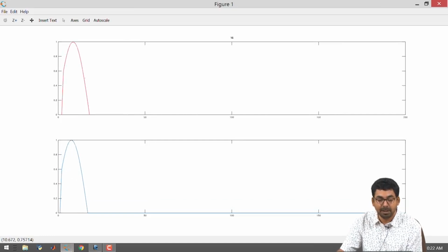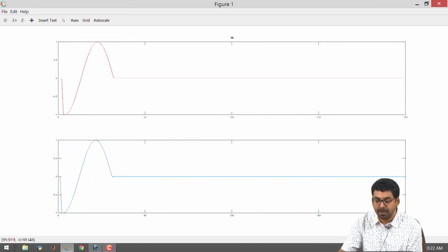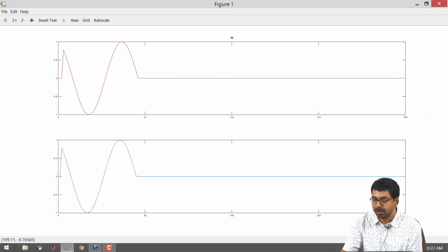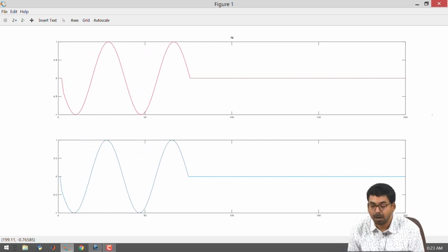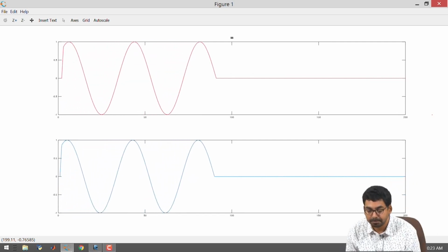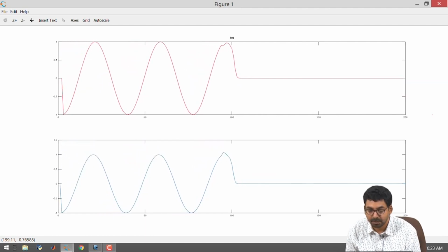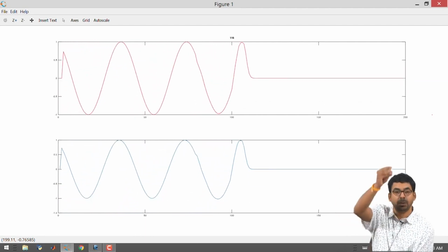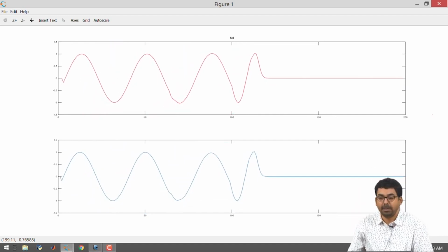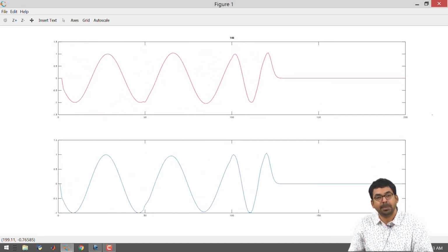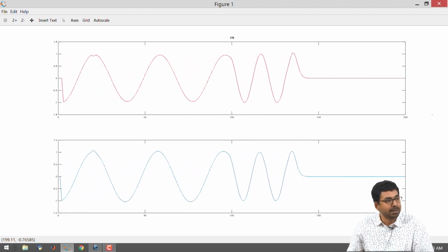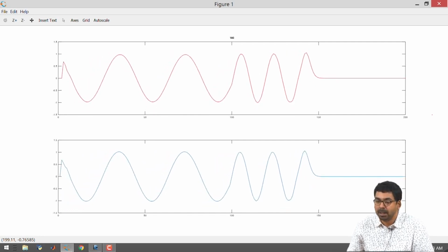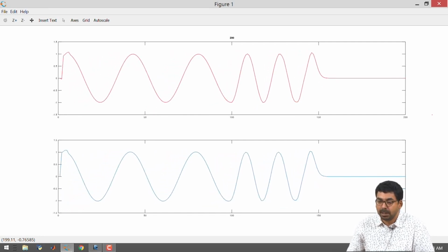So, as this wave front reaches the midpoint, you will see that a small wiggle goes on your voltage wave and also the current wave. You see something going there. That means there was a reflection. We call it a reflection due to an impedance mismatch between the transmission lines. You can always calculate the reflection coefficient and try to see what is happening. On the right hand side, we are noticing that the wavelength has shrunk, velocity has reduced.